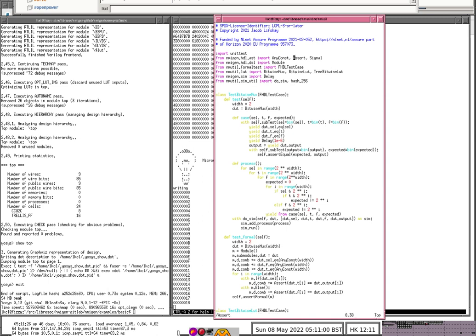One of the things that we found very handy with the formal correctness proofs is to write a simple version of a module, which is very, very obvious, and then to write an optimized version, which is not in the slightest bit obvious, and simply do, for all values of the obvious version, assert that they are equal to the exact same value of the less obvious version.